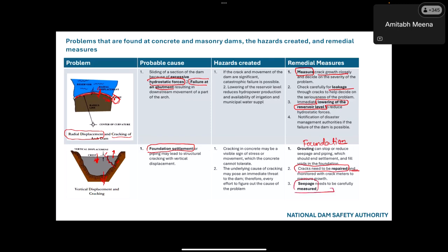It shows the seriousness of the problem. If the cracks are very fine and there is no seepage, we can fill some epoxy without lowering the dam water level. So it depends on the quantity of seepage what measures we have to take.